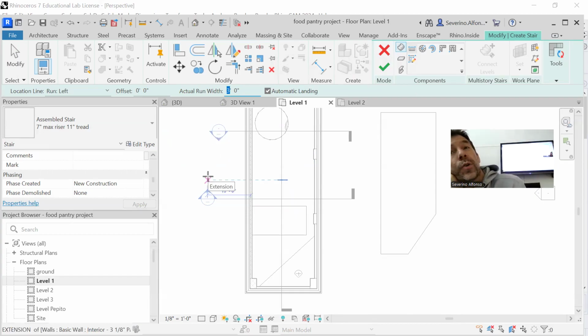So now most of you are introducing the 3 feet because it's the default stair in Revit. But unless it's a secondary private house type of thing, a basement stair in a house, I think 3 feet tends to be small. So I will probably revise this and really question that value for the stairs that you're doing.